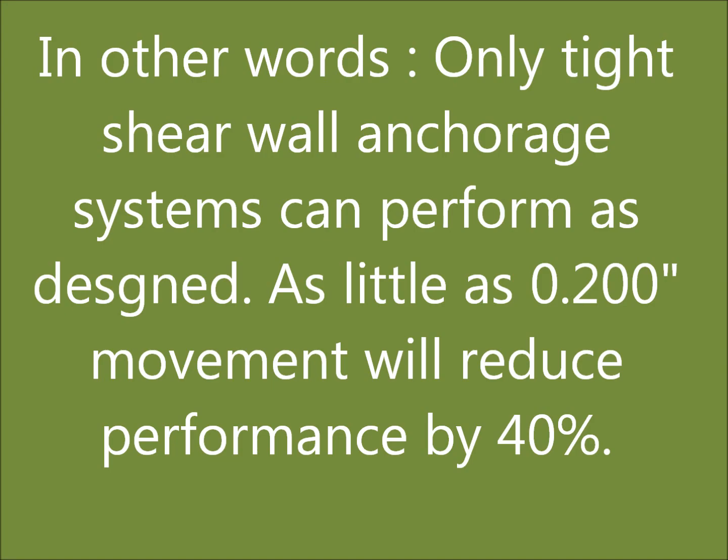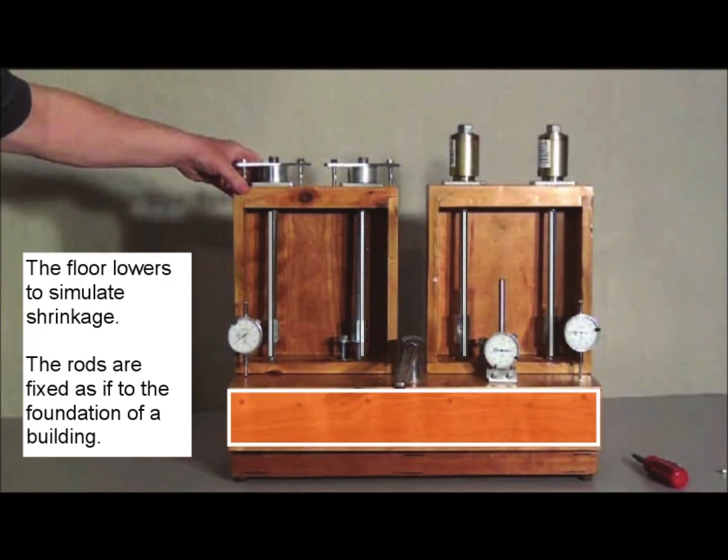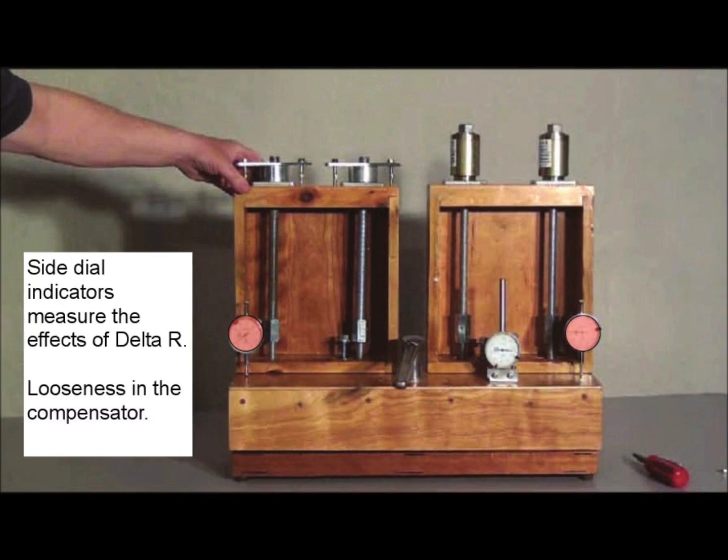To demonstrate delta R in practical terms, we will use a shrinking wall model. The lower floor of the model will shrink to simulate wood shrinkage and building settling. The rods are fixed. The middle dial indicator measures the change in the floor height. The side indicator measures the delta R movement with respect to the shear wall due to the shrinkage compensators.